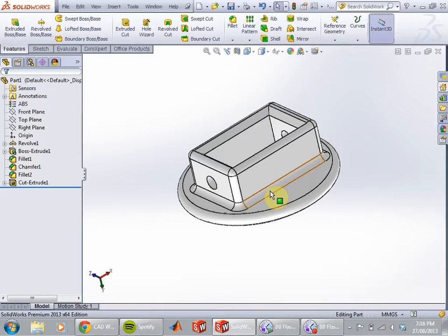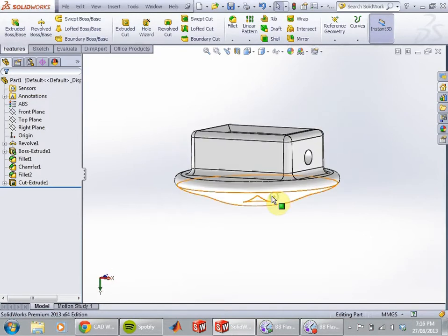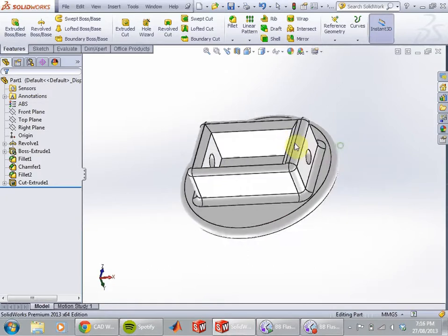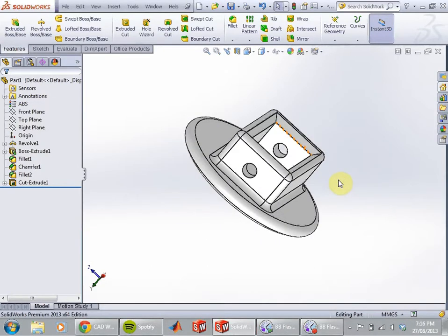Yeah, so it's more about making sure you think about how you're going to take this fill material out, and how much fill material there is, and how easy it's going to be to take it out. This hole here, it's quite easy to take the material out. If the hole was covered on this side, and this whole part was covered, you can't get to this fill material easily. So you just have to think about getting this fill material out. It's not very easy.